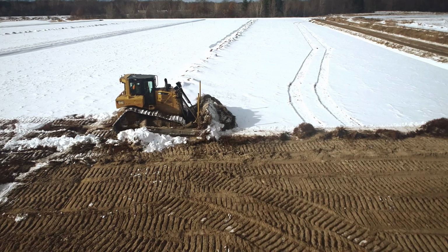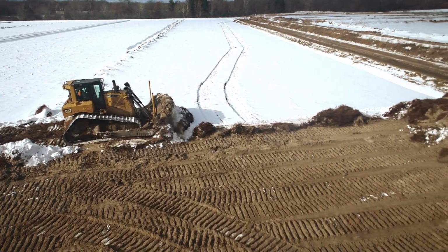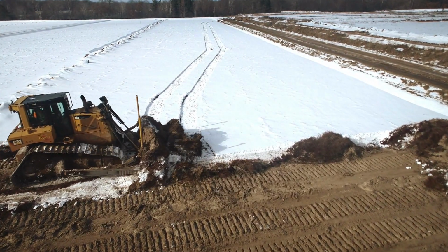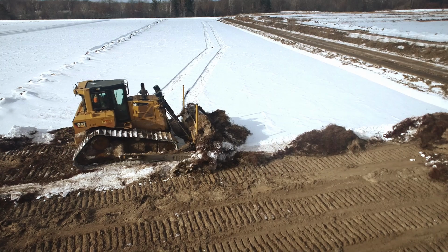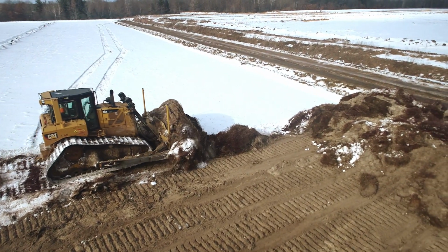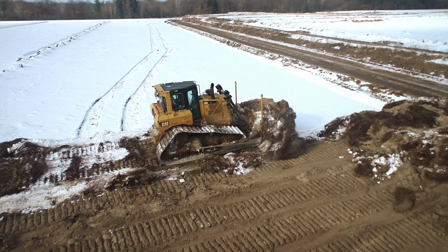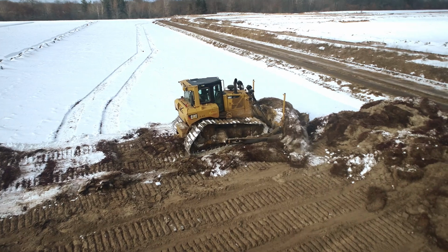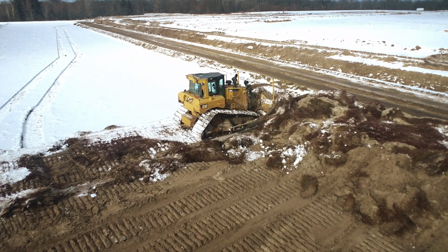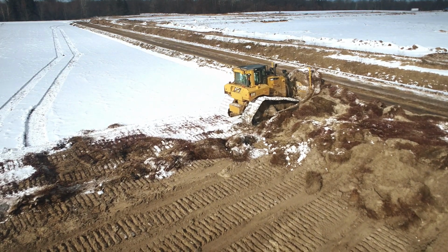Specific to frozen conditions: ripping is to be done in first gear and the ripping pattern as directed by the supervisor. The ripper is not to be used for breaking up frost lumps. Never work alone near frozen ponds, sumps, or ditches, and never work or travel parallel to the crest on frozen slopes. Never travel on frozen slopes or ramps without proper preparation, always maintaining safe footing of the machine.